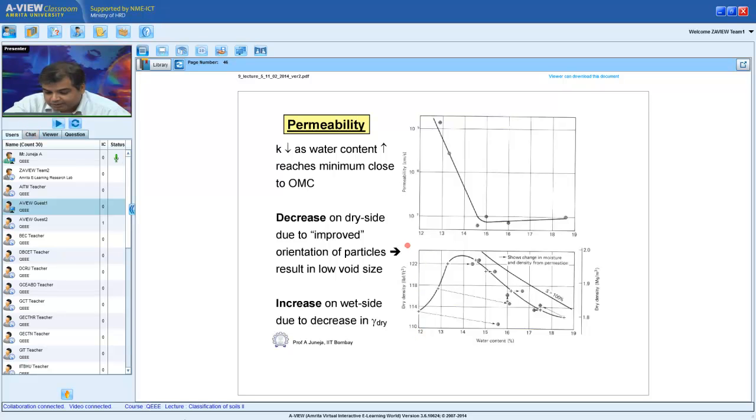Okay, on this slide, the bottom figure shows the dry density or the dry unit weight. I would not like you to look at the numbers. Numbers hardly matter, and the horizontal axis is the water content, and that's a nice compaction curve. Probably for a silty kind of deposit with some amount of clay. So as we see, with the increase in water content, you had a peak.